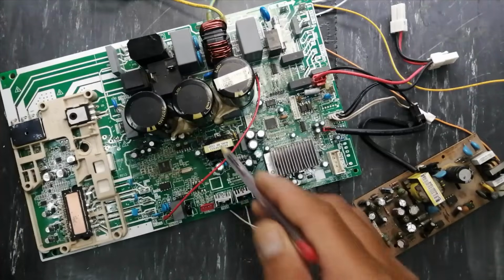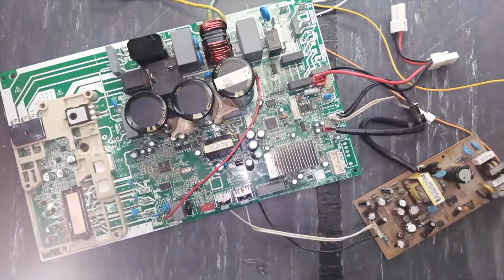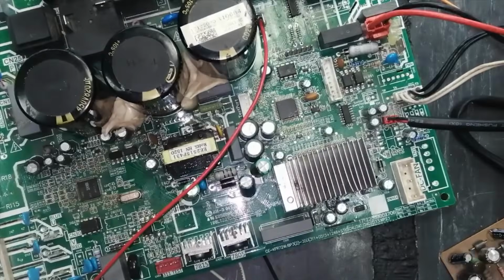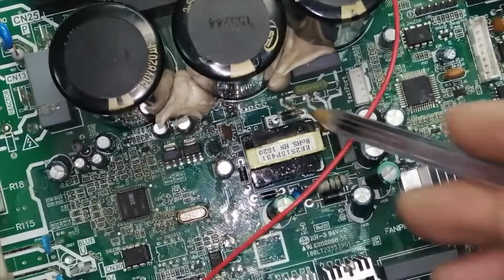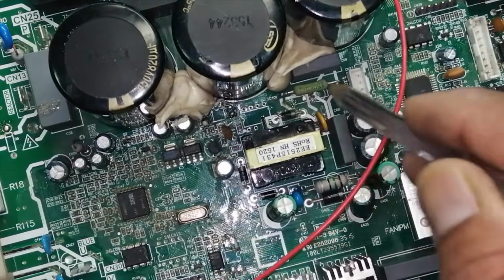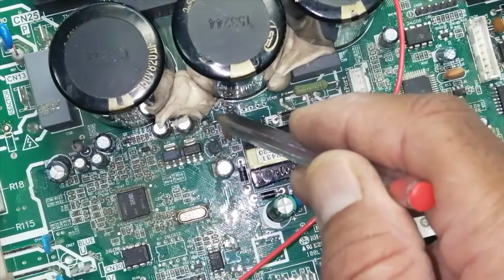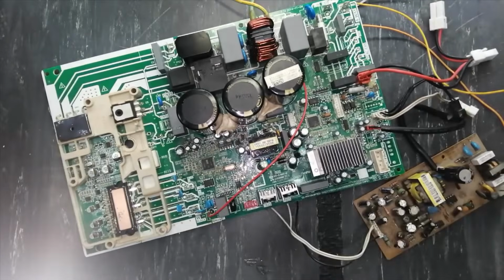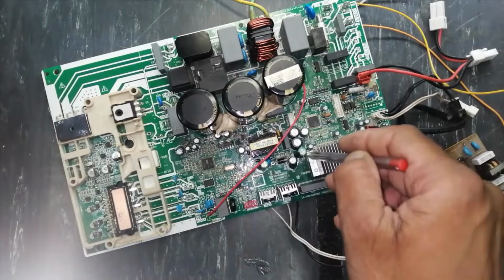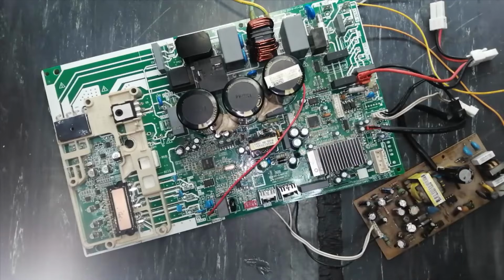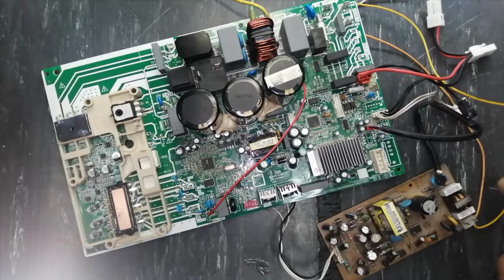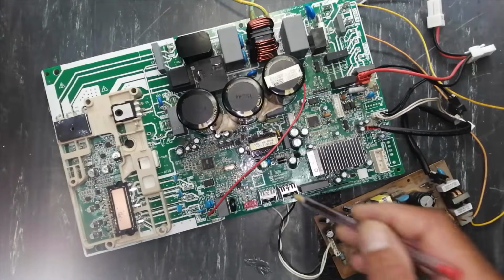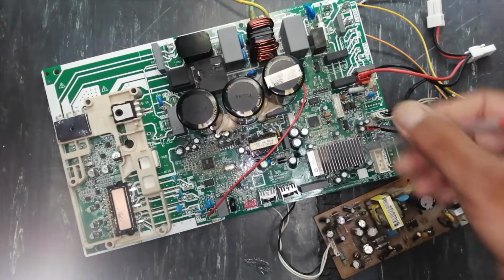So friends, as I discussed, this circuit does not have a PWM controller because its PWM IC is burnt out and it has some problem in this area. Optocoupler is missing. So what I did to show you the function, I bypassed this SMPS. This is an external power supply, this is for a satellite receiver. I connected this power supply and I will show you the connection.